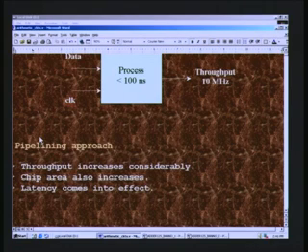And you have to pay a price for that. The price is not very heavy, it is just an increase of some chip area, in the sense that we need to have what are known as pipeline registers, which we will be seeing shortly, and because of those registers the chip area will increase. And in addition to this, even in the conventional approach, if you apply data, the result comes out only after this delay of 100 nanoseconds.